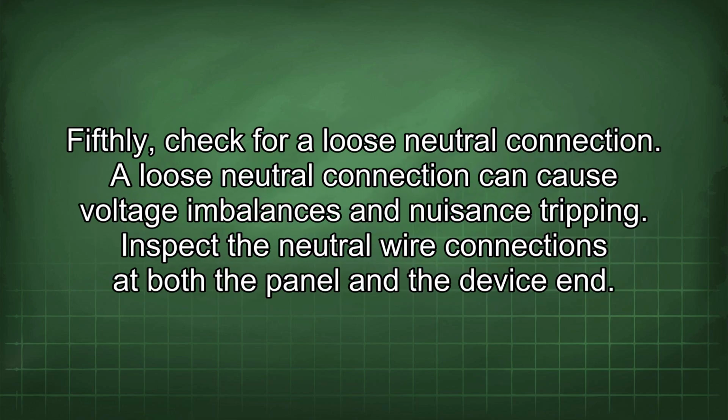Fifthly, check for a loose neutral connection. A loose neutral connection can cause voltage imbalances and nuisance tripping. Inspect the neutral wire connections at both the panel and the device end.